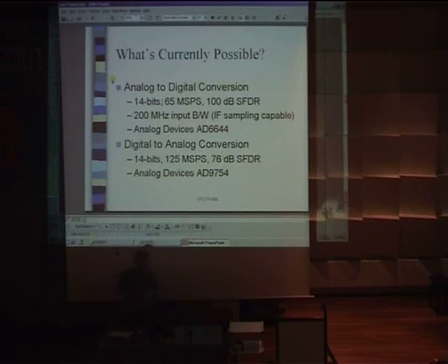So now what's pretty interesting is if you look at, for example, the cellular market in the US, we have an A operator and B operator that are adjacent in the frequency allocation, and the two of them together take up 25 megahertz. So you could conceivably build a unit that has a no-tune front end, a fixed tuning front end, and with one RF front end and one A to D converter, you can pull down all of that data all at the same time. This is the key piece to this whole game: all of the data all at the same time. There are no knobs to twist on the RF side of the thing.